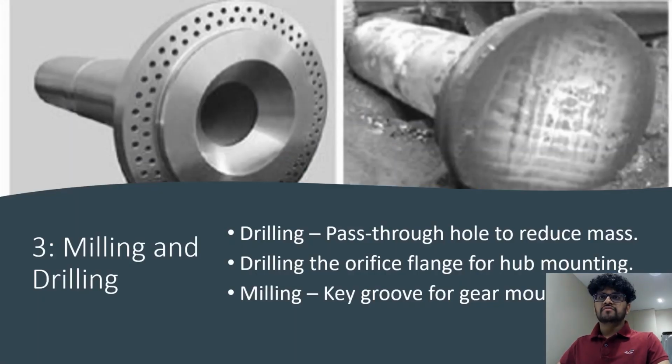For the next step, finer features such as pass-through holes, mill holes for demounting, and the key grooves are achieved using drilling and milling processes.